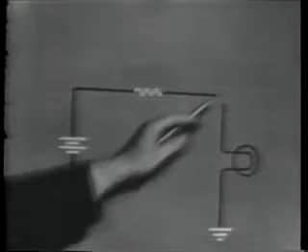Now, here's a circuit quite similar to the one I showed you before. It consists of a battery, a resistor, a broken wire connected between the resistor and lamp with the lower lead of the lamp connected to ground. Since the lower lead of the battery is also connected to ground, this amounts to connecting these 2 leads together, which makes this circuit the same as the previous one. Let's call the open point A.